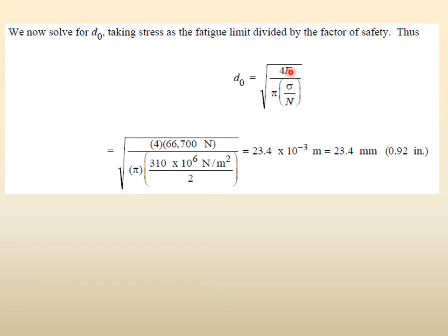So the load was given, remember, the load was given, yes or no? What was given? If you go back, one of these things is given in the problem, and the other you read from the graph: at the endurance limit, what is the stress amplitude. So you directly put it in there and you get this answer.